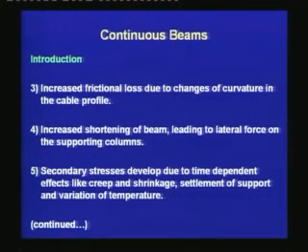The fourth disadvantage is increased shortening of beam leading to lateral force on the supporting columns. As the beam shortens due to the effect of creep and shrinkage, this will induce some forces in the supports, and these forces need to be considered during the design of the supports of the beams.